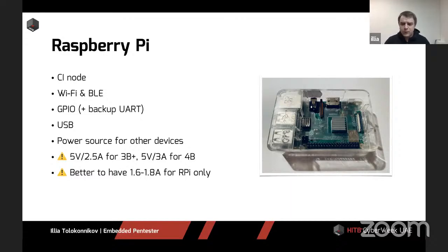We went with a conventional Pi instead of the Raspberry Pi Zero, because the Zero has GPIO outputs you have to solder on top of it. With USB, it's a whole different story. We connect a lot of things to USB, and both USB and some pins on the header can be used as power sources for our devices. Some of our devices can be powered easily from 5 volts and up to 500 milliamps, so we use USB on the Raspberry for those. And some other things can be powered from the 5 volt and 3.3 volt pins on the Raspberry itself.